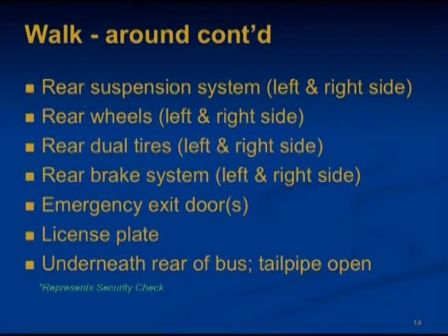The brake drums, check for cracks, dents, holes, missing or loose bolts. The brake linings, where visible, should not be worn dangerously thin or soaked with oil.